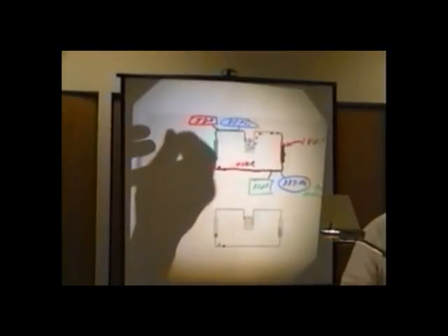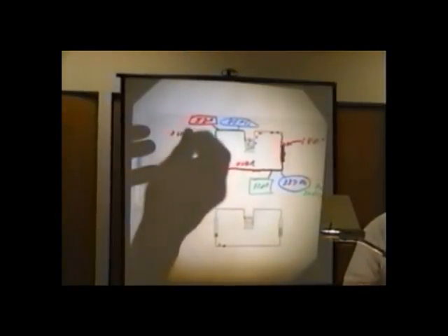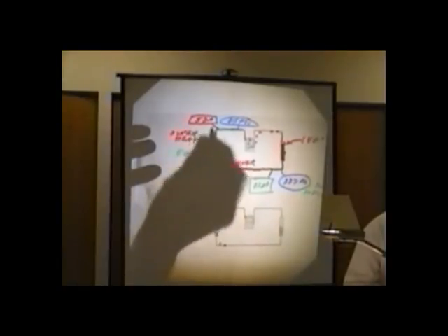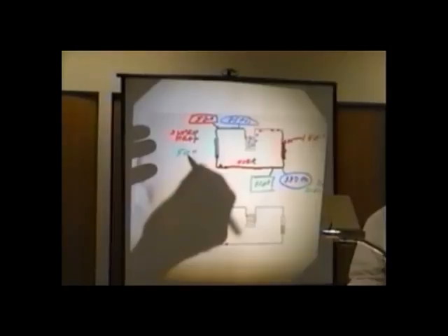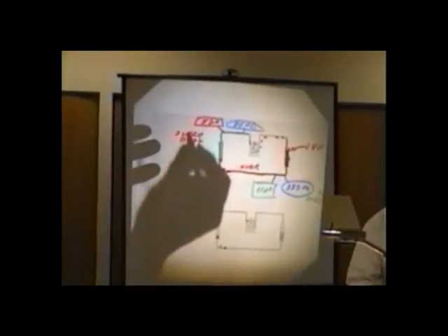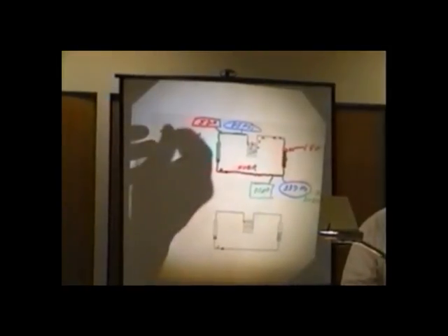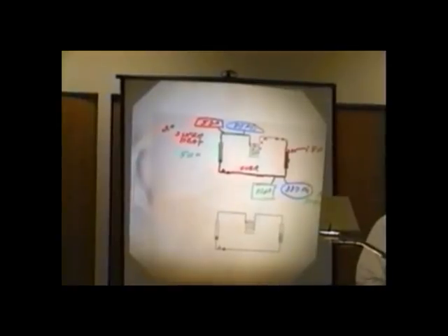And I have 52 degrees. Suction line. How many degrees of superheat? 2. 50-degree evaporator, 52-degree suction line. I got 2 degrees of superheat.